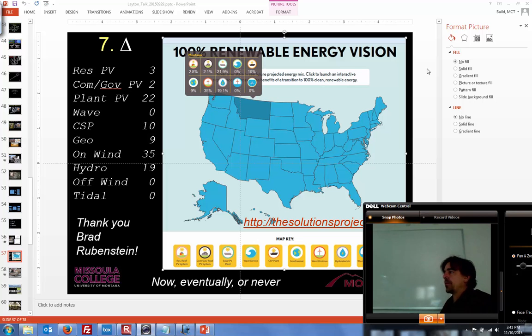So for example, it is possible to overexploit a geothermal system. If you pump heat out faster than nature is putting it back, your geothermal installation might run out in 20 years, and then your payback that was supposed to pay you back in 30 never happens.